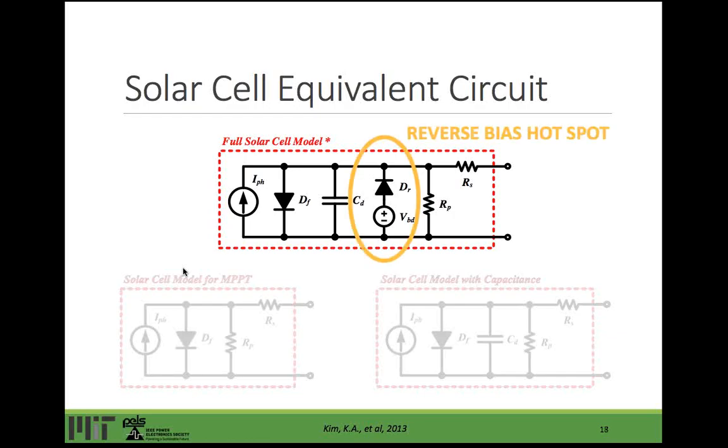Now typically, when maximum power point tracking is considered, we're referring to a particular DC operating point. So the model is oftentimes simplified to what we've shown before, where the capacitance becomes an open circuit, and because we're under the assumption that we're extracting power from the PV element, reverse breakdown characteristics can also be removed. But for our purpose today, we're trying to figure out if we can leverage any parasitic component as a potential energy storage device for power processing. So we'll reintroduce a parasitic capacitance back into the model, and this is the model we'll be using moving forward.